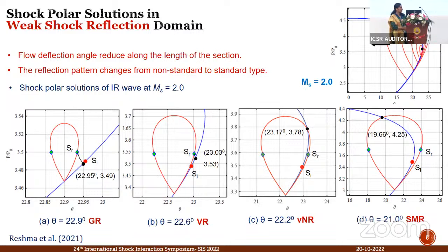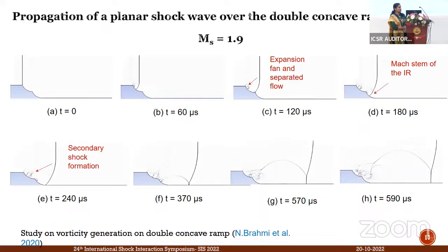But what we will look at is, as an irregular reflection is formed here, what is the flow Mach number? We'll be just looking at the speed of this shock wave in the plane section and transforming it, because we are not concerned about what flow happens here. But if an irregular reflection is formed here, that particular speed will be used for transforming.